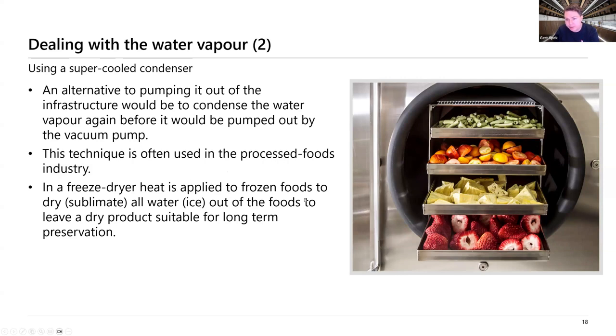So a freeze dryer is in essence a combination of a vacuum tube, often at below 1 millibar pressures, food that is frozen, heated plates to introduce the heat, that's our waste heat that we try to reject, and then a condensing system where this water vapor can sublimate out of the goods, leaving dried goods behind. As I said, from the triple point, there is no liquid water, and liquid water is what gets products mushy. So in essence, it behaves similar to dry ice in these conditions.